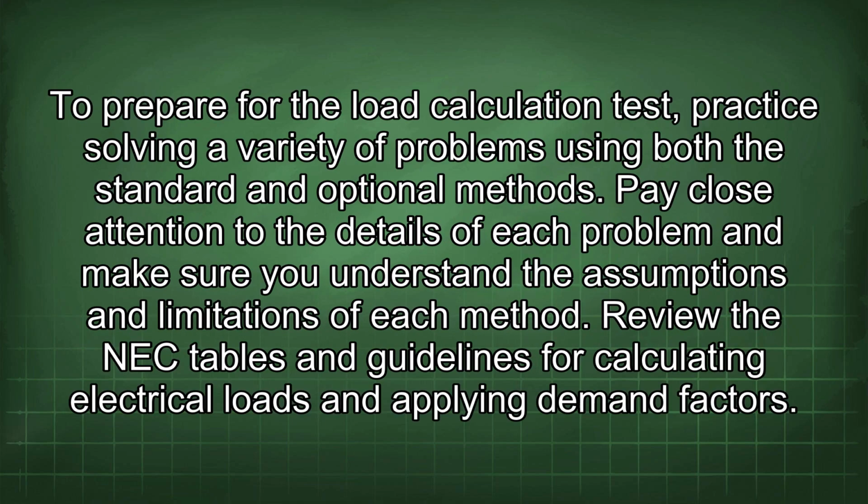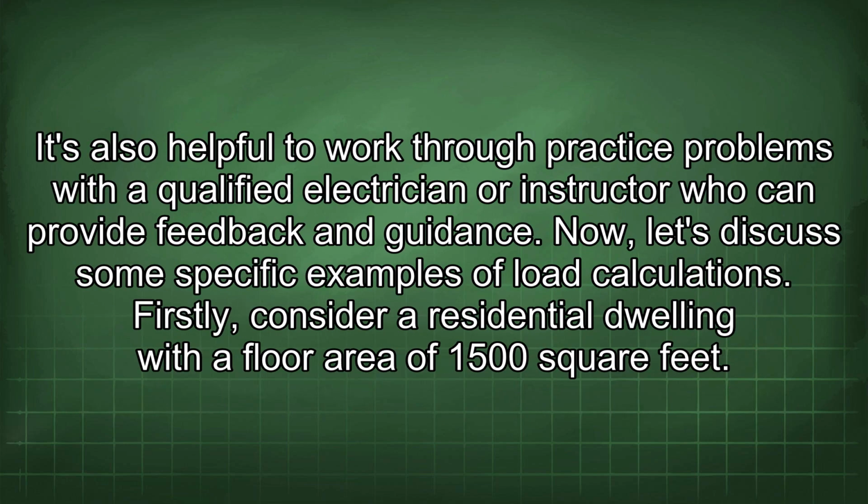To prepare for the load calculation test, practice solving a variety of problems using both the standard and optional methods. Pay close attention to the details of each problem and make sure you understand the assumptions and limitations of each method. Review the NEC tables and guidelines for calculating electrical loads and applying demand factors. It's also helpful to work through practice problems with a qualified electrician or instructor who can provide feedback and guidance.